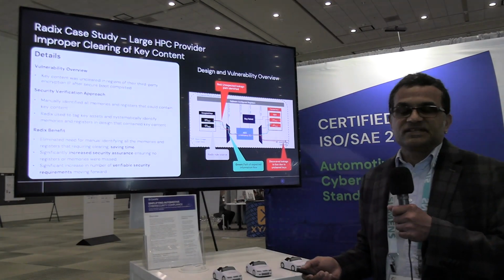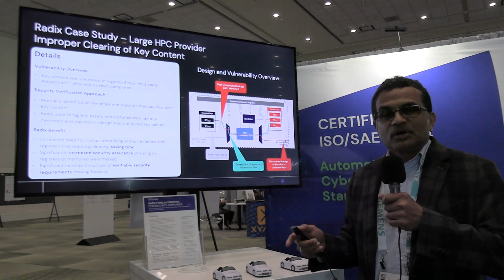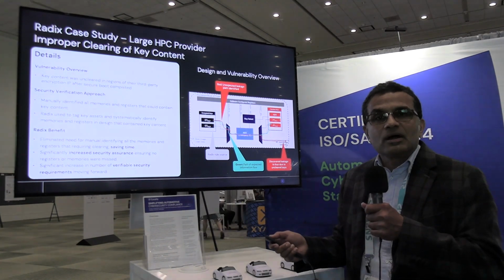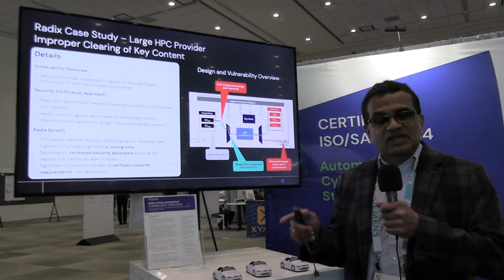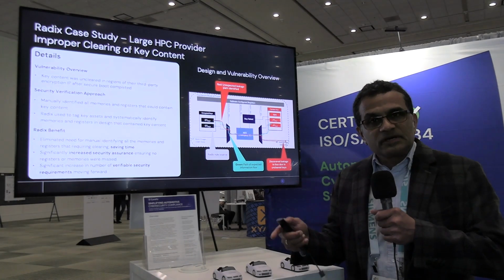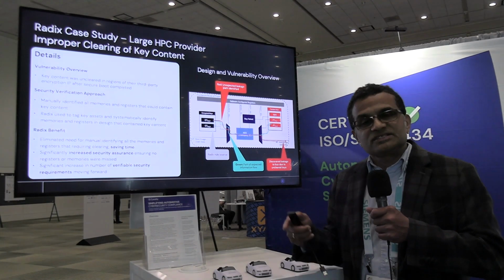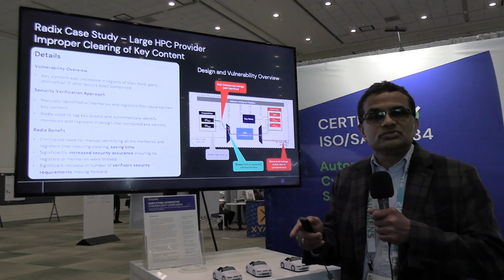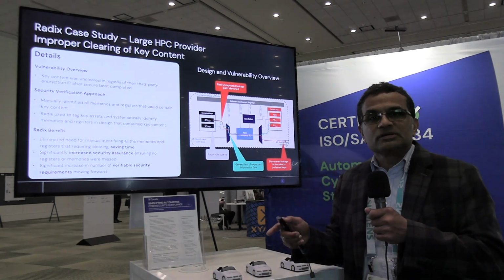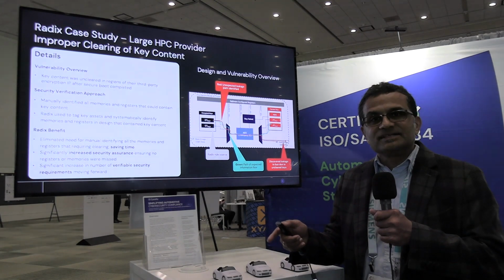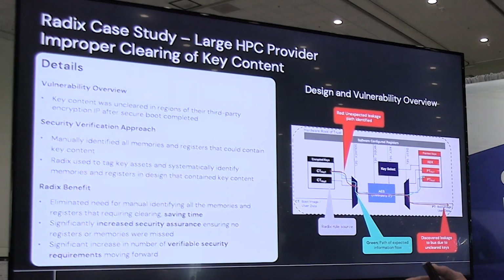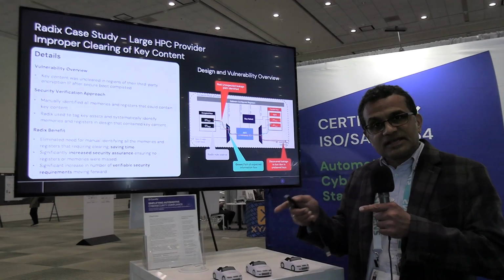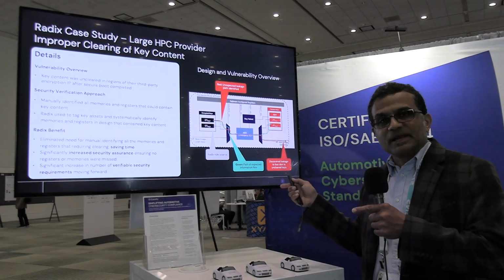So the worry here is that there is a possibility that the cipher key can actually leak out on the plain text bus. Remember, this design has two functionalities. One is to take cipher keys, decrypt them and store them in an internal key table. And then the second functionality is that it can actually use user-level firmware to be decrypted in the AES block and then sent out on the plain text bus to the block that follows. So the worry here is that the cipher keys that get decrypted, and somehow there may be information that leaks out from the AES block all the way down to the plain text bus.